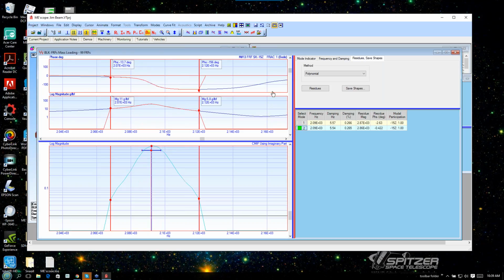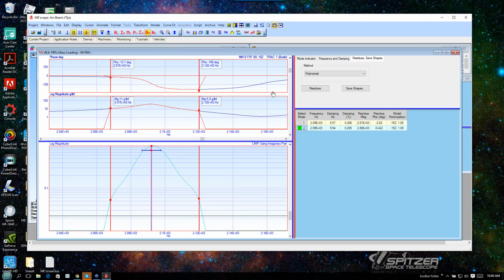Okay. Anything else? Okay, yeah, I got a follow-on to this. It says, what I meant by accuracy of the parameters is that sometimes when curve fitting, there are some extraneous modes with damping ratios that are very far off, and I usually disregard them. What is the source of these modes? How can I rely on the estimated damping ratio? Should I use half power on some of the FRFs and compare with the MeScope values?